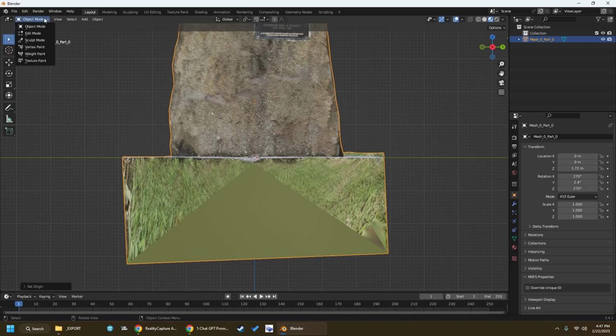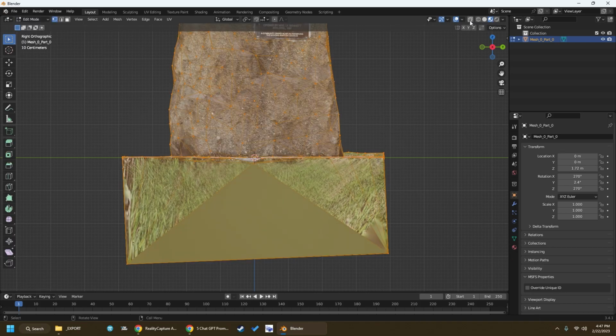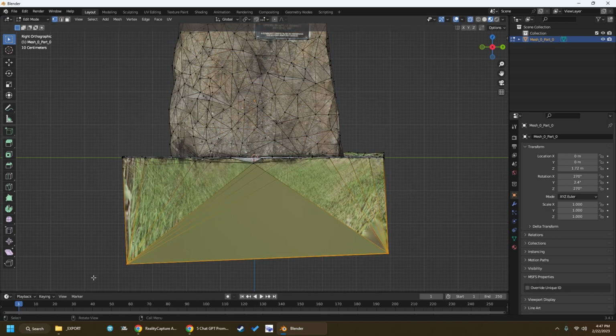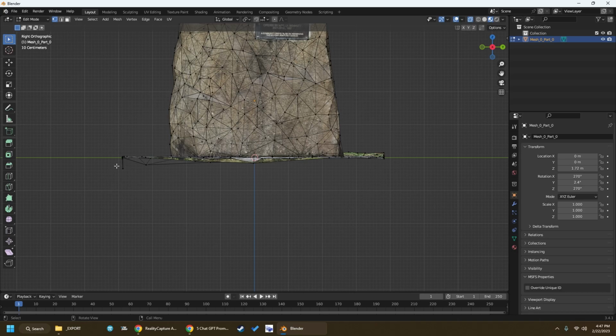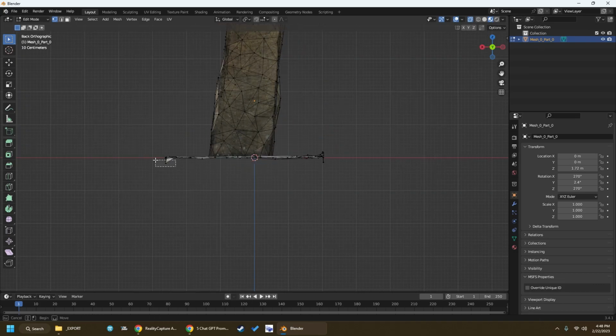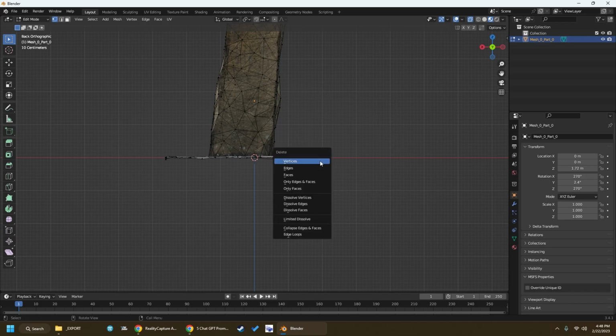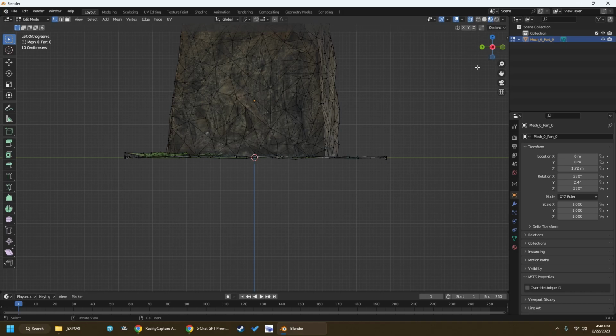So we're going to go to edit mode. We want to turn on the X-ray key because we want to get rid of all the vertices behind in our selection. So we'll go like this, click on that, it highlights all the vertices, hit delete, delete the vertices. I have a couple of spares there. I want to get rid of that one because it's not really relevant. Look at the Y-axis, get rid of that. Get rid of this one. Click on the X-axis.